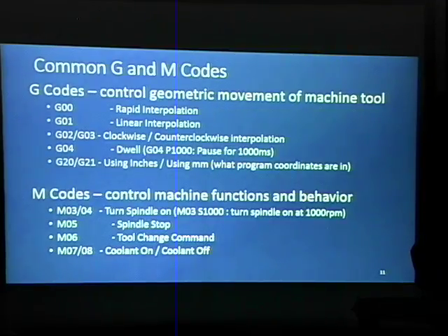The world is basically made up of straight lines and curves to some extent. So we also have G02 and G03, which allow us to move from where we are to where we want to go in a circular fashion, and we can define a radius for that curvature. Basically we're taking the basic commands required to break a physical object down into shapes, into lines that we can follow to cut them out with a metal milling machine.